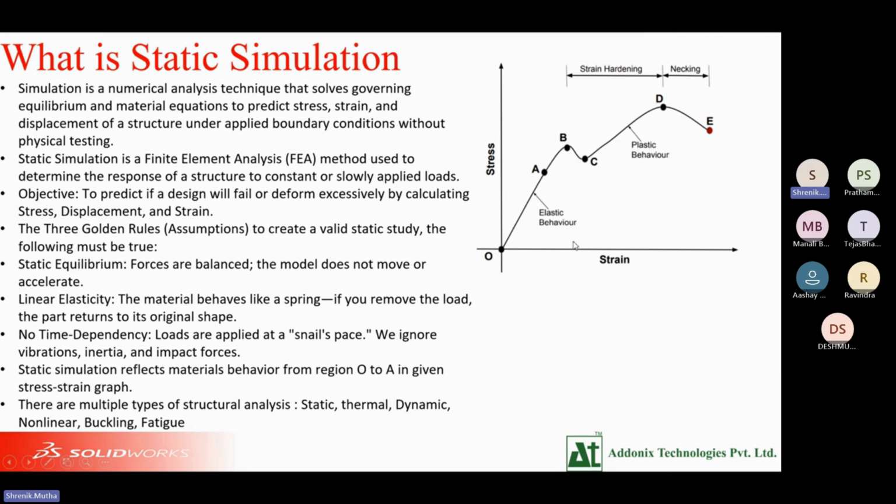Going back to the assumptions, the third assumption is no time dependency. Loads are applied at a very slow pace. We ignore vibration, inertia, and impact forces in this simulation. So as I said, static simulation will reflect the material's behavior from region O to A. This is known as the elastic region.